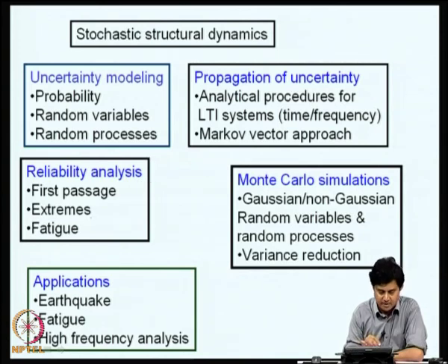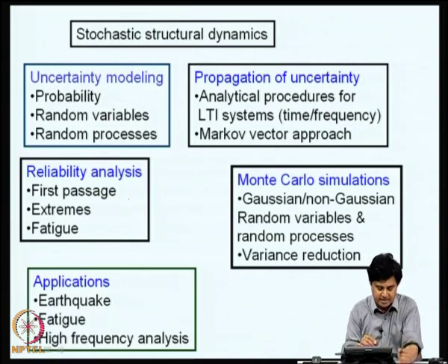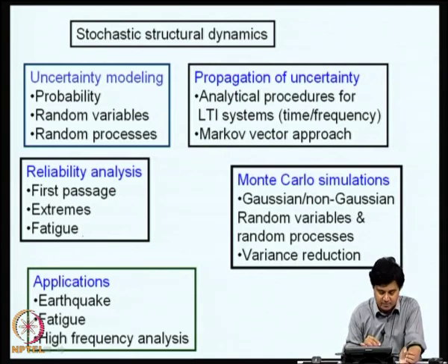Then we also considered the highest response in a given duration, that also helps us to solve the problem of time variant reliability, where we would like to find out over a given duration whether response has stayed within the safe limit or not. We briefly touched upon failure due to accumulation of damage due to fatigue. We used Palmgren-Miner hypothesis, and also very briefly we talked about fracture mechanics based approach to treat these